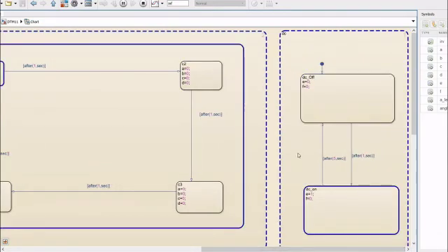Now in the state flow 2, which is the launching unit, when disks are loaded into the launching unit, the DC motor turns on immediately after 1 second, where launching of the disk takes place, and when launching of the disk takes place successfully and after 5 seconds, the DC motor switches to off state, which is this state. So this is the launching part.